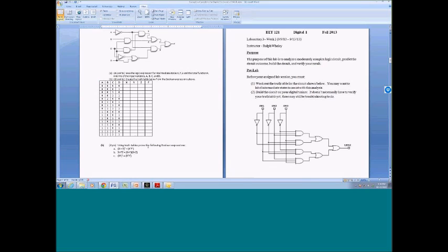These are separate things, but one of them is to prove these Boolean expressions. For instance, this is a De Morgan equivalent, and this is the second most important law, and this is that thing that I constantly see students doing. I'm trying to nip it in the bud, so to speak. So I'm trying to show that these expressions are indeed true. They can take De Morgan's law for granted, but I want them to actually show it. Just put it in truth tables and knock it out, and you can actually see that it's true.